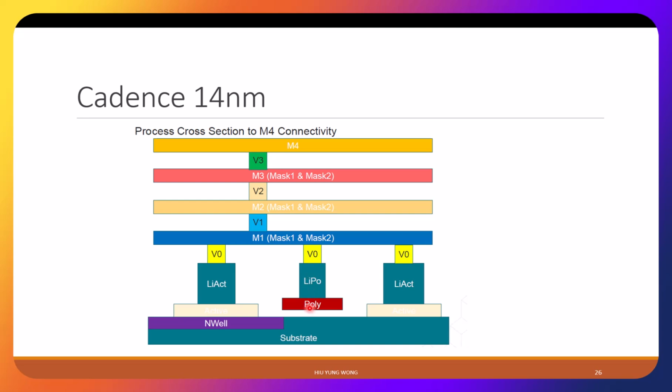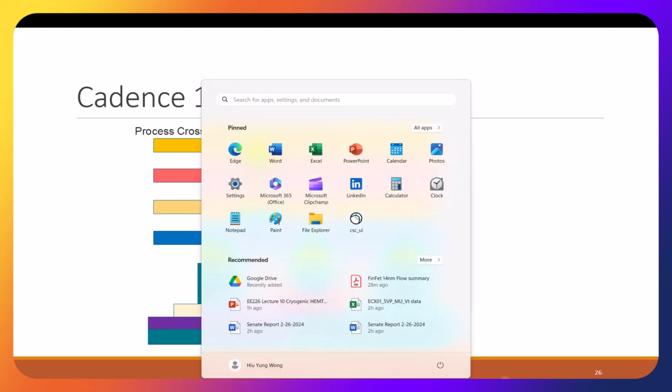No, you still need a via. This is just the definition in this PDK. You don't need a via to go from poly to Li poly. So this is particular. Yeah, because what it is drawing to you is what you will get connected. The physics is not really, you don't need a via, maybe it itself is a via. Why don't you think it itself is a via, a big via, how about that? But your via can be very long instead of just holes. So here V0, V1 are vias.